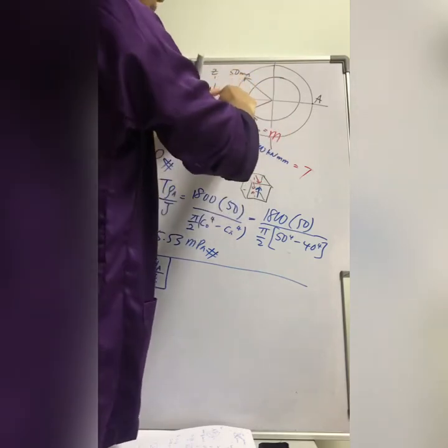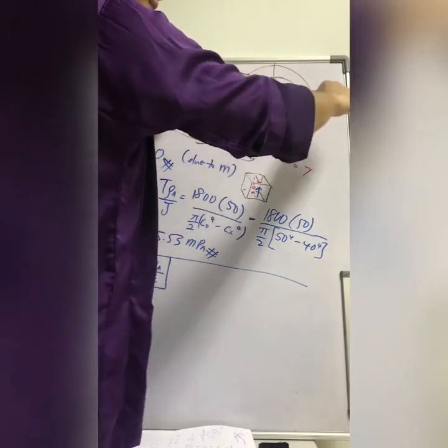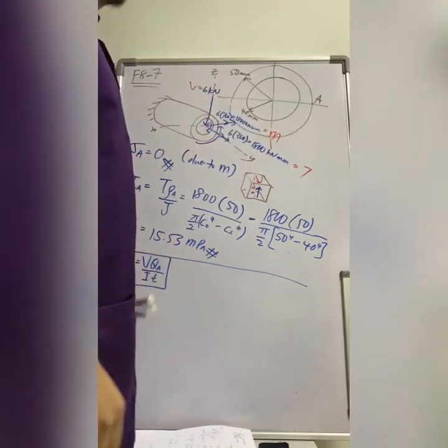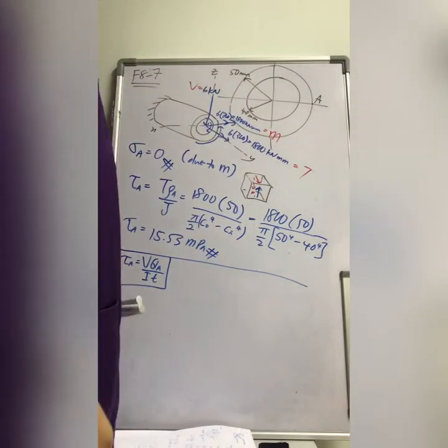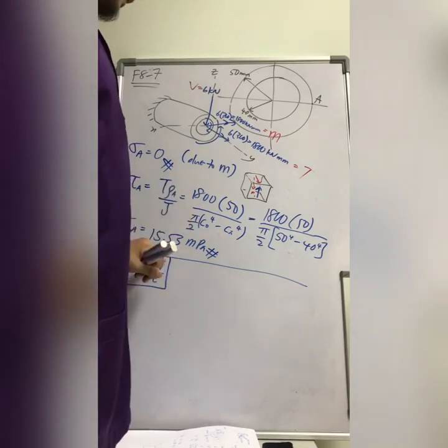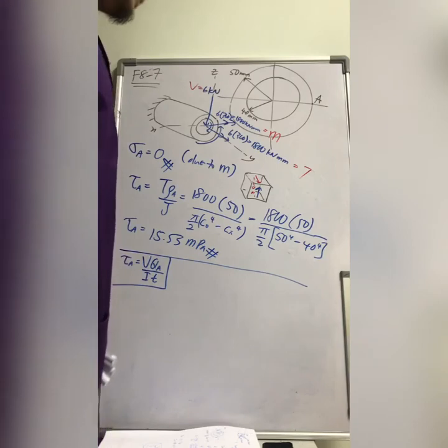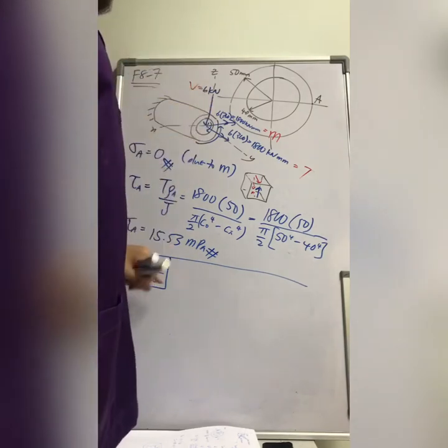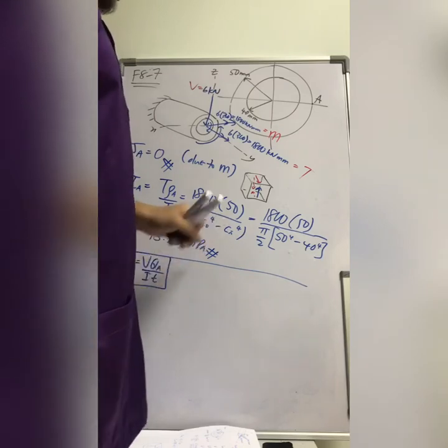So the neutral axis is this axis. This x-axis is the neutral axis. So point A actually lies on the neutral axis for this equation. Of course it is not 0, and in fact the Q will be maximum over there. So your V is 6 kilonewton. Your I, you have not calculated yet, will be calculated very shortly.